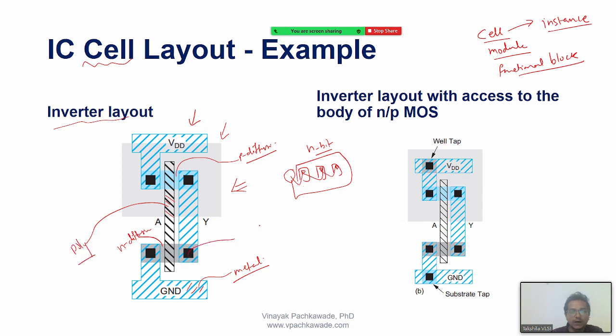And this poly, and then I have these black squares, they are what? Contacts, right? So now how are we connecting? This is my source, this is my drain. I draw it here, source and drain, and that's my NMOS transistor basically.